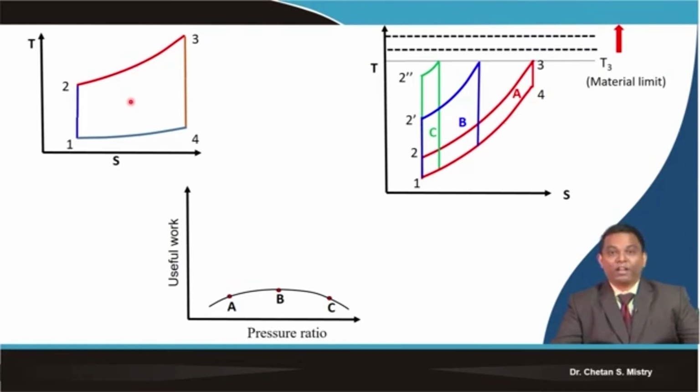Now you will say, sir, this is not giving useful work. Our expectations are different. We are looking for some other concept. So over the years, people have increased this requirement of useful work, because they are looking for higher power generation and high thrust generation. So this is representing the increasing trend for your pressure ratio in relation with your useful work.